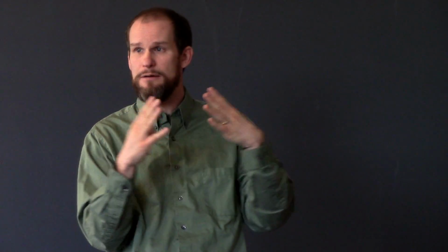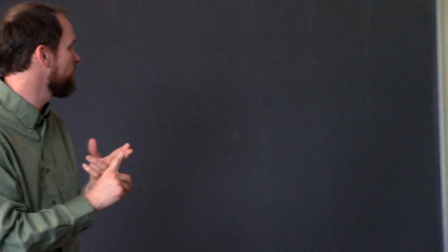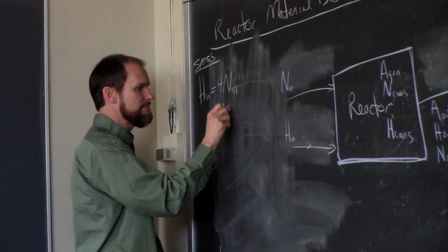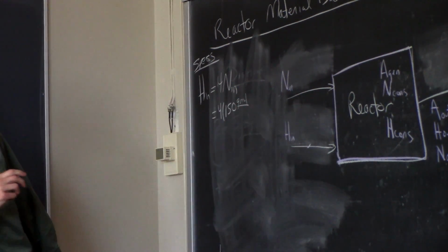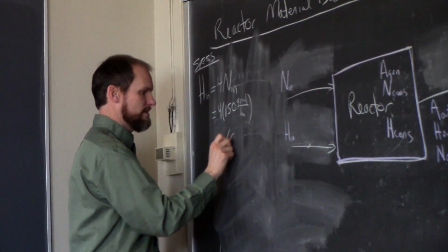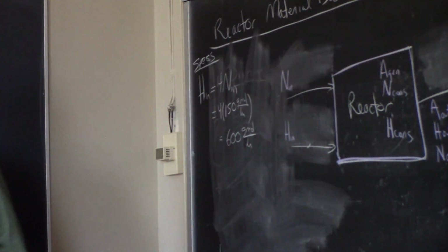This is where our diagram is a little funny. It's actually one mixture stream going in. It's talking about that composition. Great. Okay, then from that, you're right, Ebony. We know N in, so you got 4 times 150 g-mole per hour, so you got 600 g-moles per hour of hydrogen in.